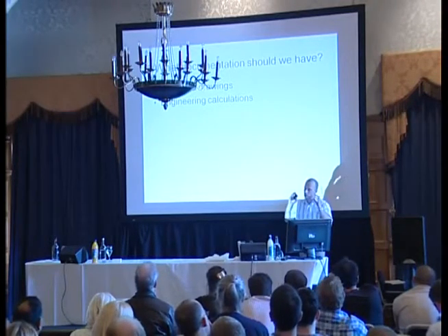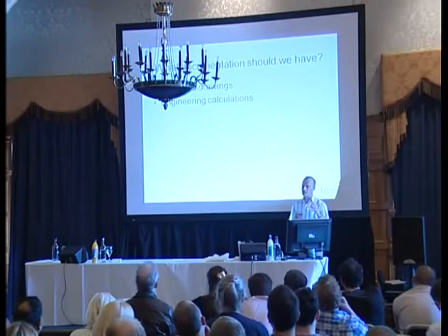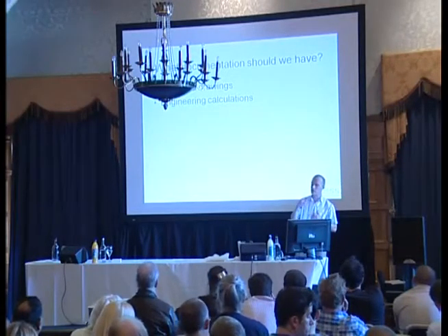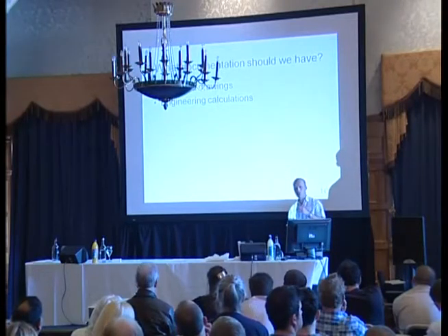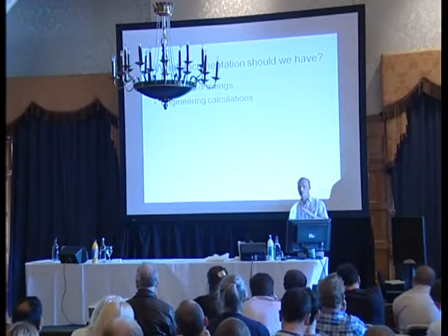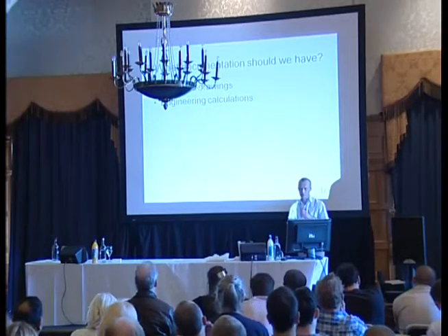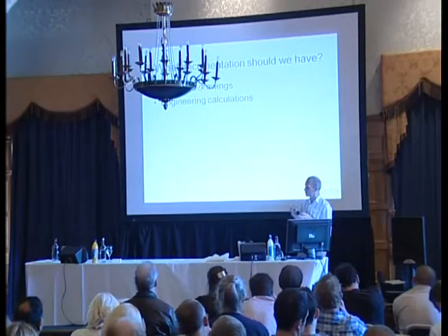I don't care where the wind comes from. If it's going to blow down in those wind speeds, I need to know, because then we get a managed wind plan that means we can make sure that we have cleared the site if we are getting anywhere near those wind speeds.